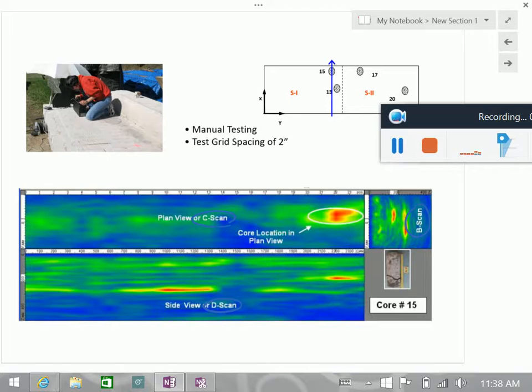You kind of want a surface level. Right, but ultrasound doesn't give you really anything near the surface. If you're very close to the surface, there's a blind zone. So it's not a surface measurement. In surface, you can see what's going on. So all C scans, it's always like the depth is specified.